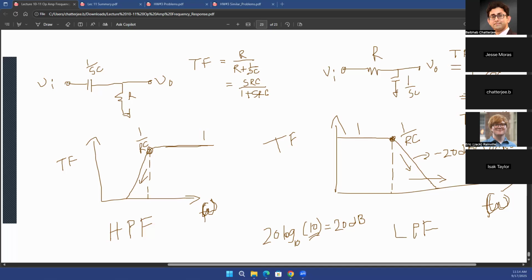If you have a higher order transfer function, second order, third order, fourth order, all that means is that you'll have more number of poles. So if you have 2 poles, it becomes a second order system. 3 poles, it becomes a third order system, and so on. And in that case, the effect of S is going to be multiplied. In this case, the S was having a one-time effect. If you had S squared, that will have a squared effect. If you have S cubed coming from 3 different poles, that will have a cubed effect, right?